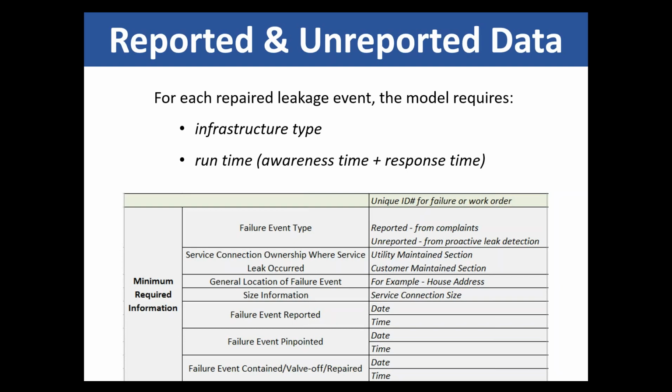We're pretty agnostic to everything after flow containment. If you spend a couple of days paving, great. That doesn't really pertain to water loss. So we're looking at the time from awareness to containment. There's also a modeling option for the discovery time, between when the leak first started and when you found out that it existed. If you haven't done very detailed research-like work, you'll likely work with the default assumptions in the model to account for the full duration of the leak. So for each event, you'll report the infrastructure, the size if it's a main or a service connection, the duration, and then you can either work with your own flow rates or some defaults in the software.